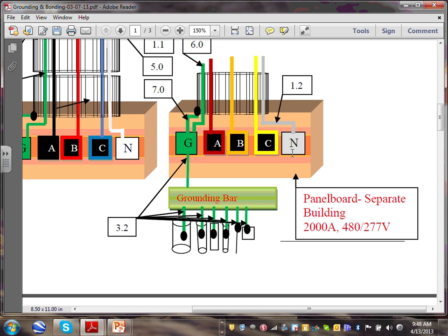Does anybody have an inspector that allows you to pull a conductor to a separate load outside without an equivalent conductor? I can't think of any location. Do you? Existing. And you pull the cable? Yeah, existing cable, yes. So it's really the exception. The rule is you pull an equivalent ground conductor and you isolate the neutral from the ground.